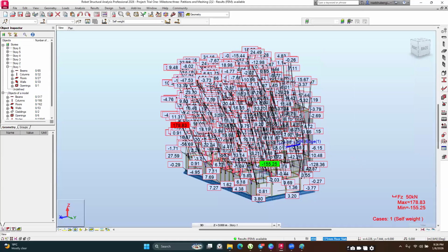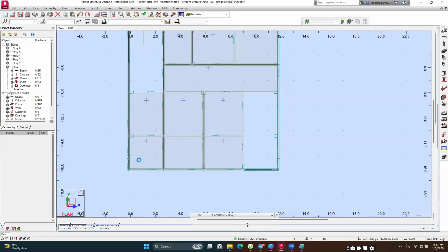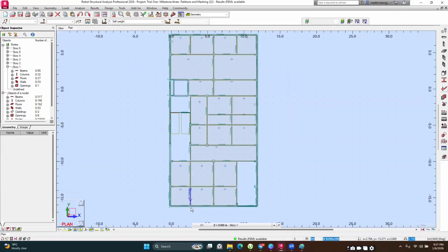So at this point, it is quite jumbled up and you cannot understand this properly. So to see them view by view, you see where you have your 3D view, you can work with the YZ and XZ. So when you choose YZ, this is Y. So you are viewing beams along, say, this direction and Z only, not in 3D. So you are cutting a section along Y, and it's going to show the Z elevation. And then in XZ, you're cutting along the X.